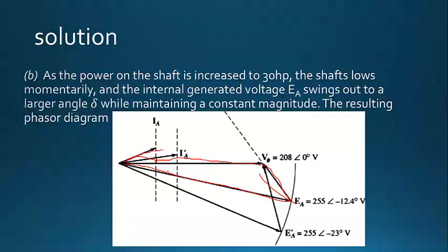And one particular thing that we will take note of is that delta has increased. Delta was 12.4. Now delta has increased to 23 degrees, because there's been increase in load. So the torque angle should also increase. We made mention of all these things in our previous video.